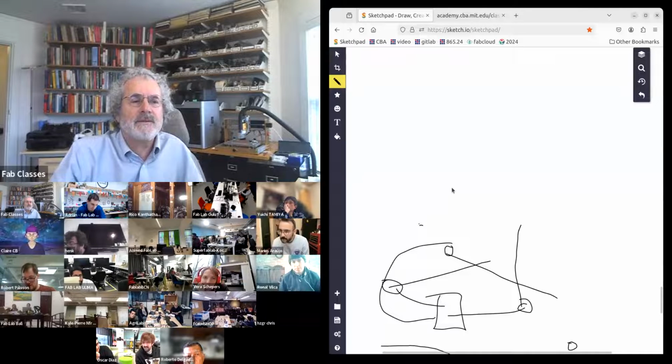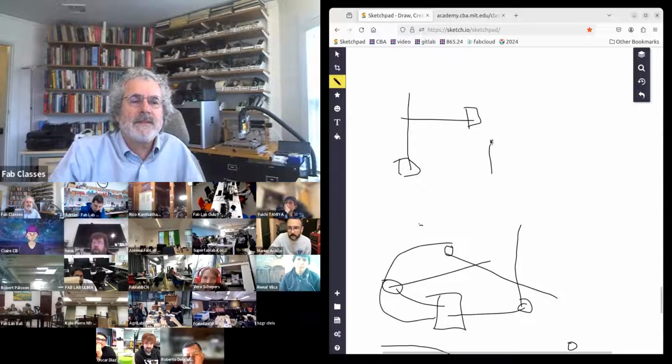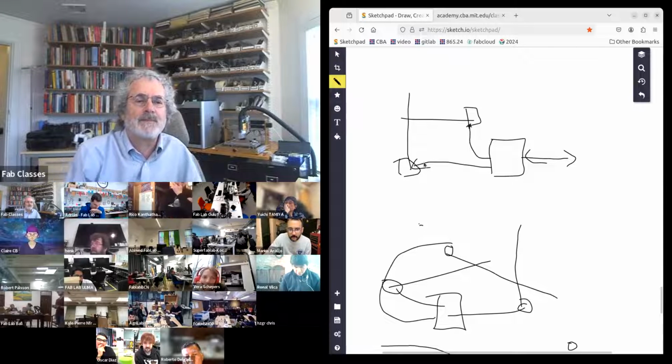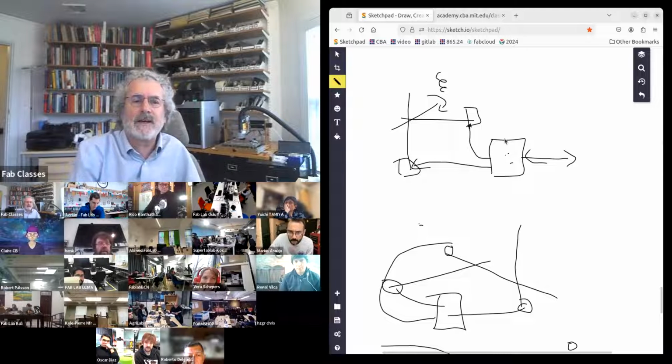In a traditional machine, like I just sketched here, let me draw this more carefully. Let's say we have an x-axis with a motor. We have a y-axis with a motor. This is the machine controller that connects to your computer. And then this connects to all the degrees of freedom. But let's say you wanted to add a z-axis, and a rotary axis, and a screw extruder. If your central controller doesn't have those inputs, you're stuck.